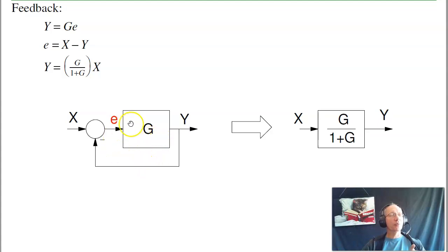There's only one frequency where the signal adds in phase. If the gain at that frequency is bigger than 1, you get your screeching, the feedback. That's unstable. Again, that's a feature in this class. I can take a perfectly well-behaved system and make it go unstable. The trick is, how do I design it so that it's stable and meets my design specs?